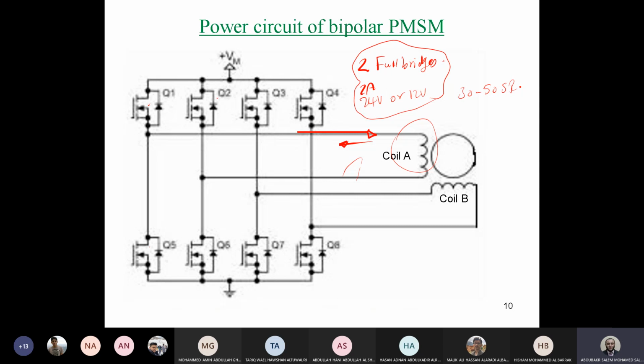So in this circuit, guys, we have to consider that the source, which is this terminal of the MOSFET, for all the upper MOSFETs, cannot be connected to the same ground, because if you do that, it will short-circuit the coils.